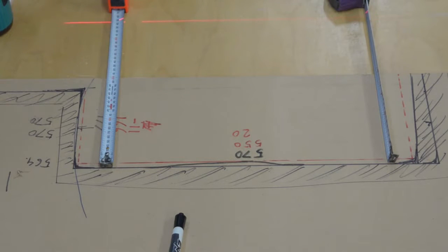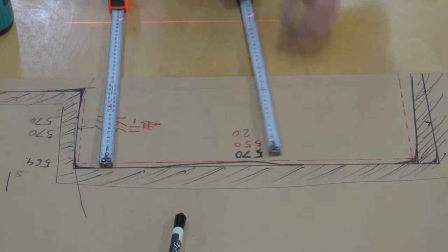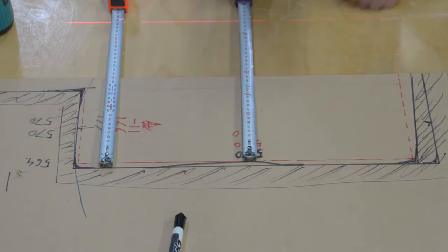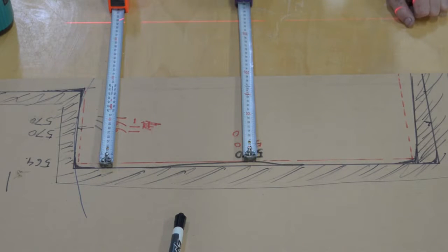So I'll set this up so both ends are saying 350 at the deepest. That's pretty good. Both tape measures are reading 350, which means I can go along and try the wall in various places. Okay, there's a bump there. That's measuring 340. So we've got the same story being told whether I use the laser or the straight edge. So there's two possible methods of assessing the flatness of a wall.